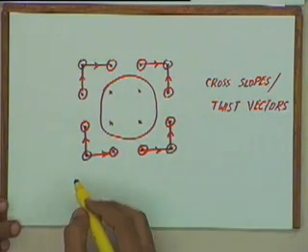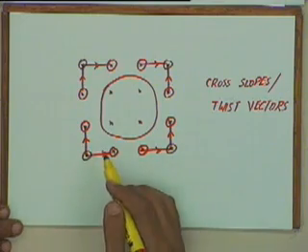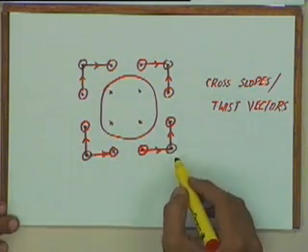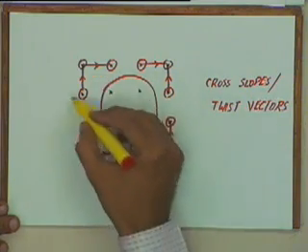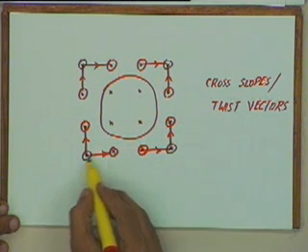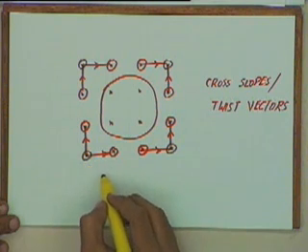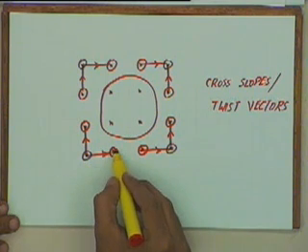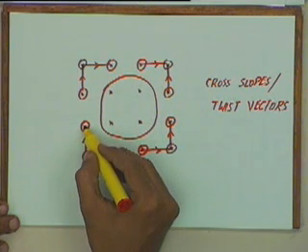And again we can say something we said earlier for Bezier curves, that if I am given this array of input points and I change any of these points, my tangent vectors at this point will not get affected. So at this point the tangent vector in this direction will be controlled only by these 2 points, and the tangent vector in this direction will be controlled only by these 2 points.